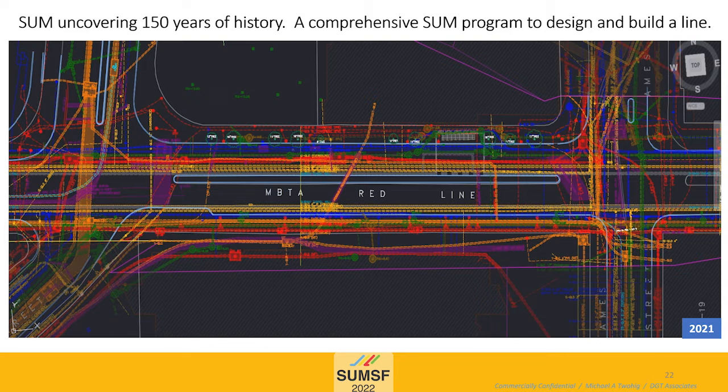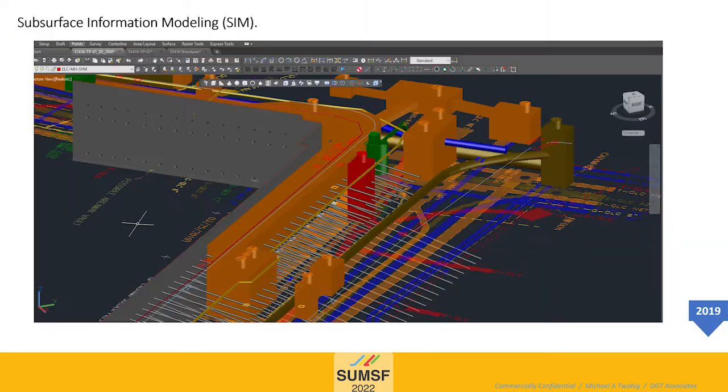This is a document that's done, color-coded. It's American Public Works color coding. All of the lines are annotated to conform to the ASCE standard 38-02. And this is typically what we do: make sure that every line is represented not only with its annotations for reliability, but also for a number of conduits. Asset owner information is added where possible, and it completes the picture for the underground.